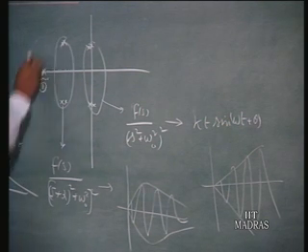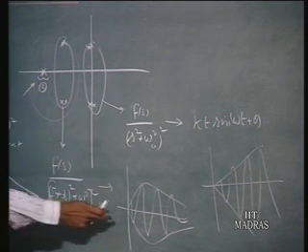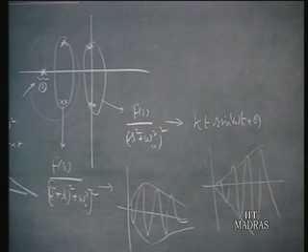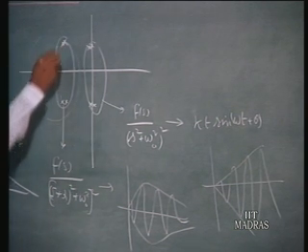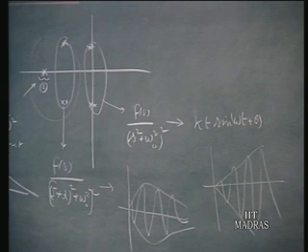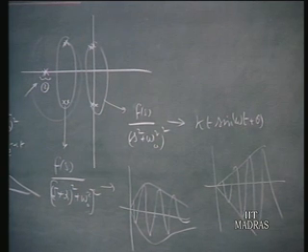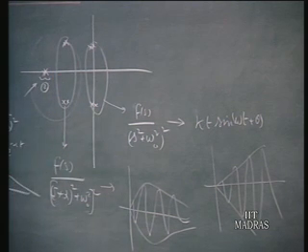But as far as the left half plane is concerned, what we have illustrated for order 2 can also be extended for higher order. That means you can have a pole on the negative real axis of order 4, 5, 6, whatever it might be, and similarly complex conjugate poles in the interior of the left half plane can be of any order whatsoever. Ultimately the response will decay. On the imaginary axis, however, you can have only simple poles.